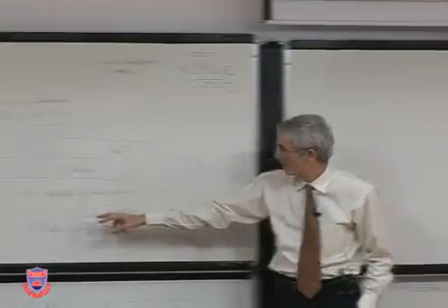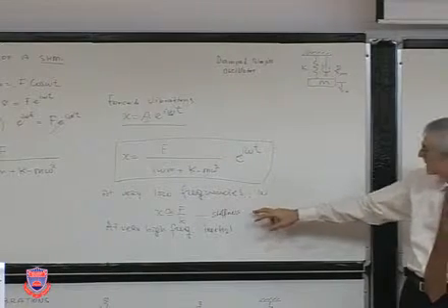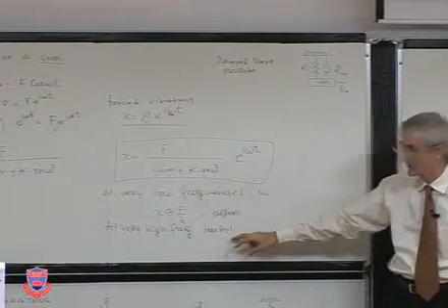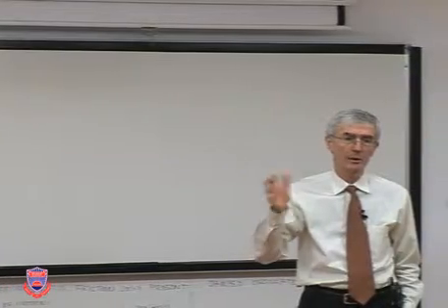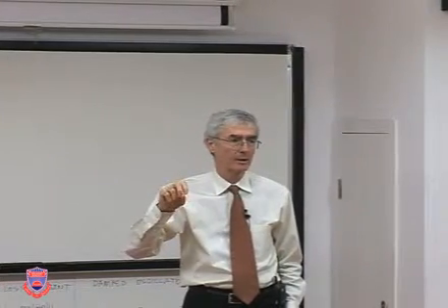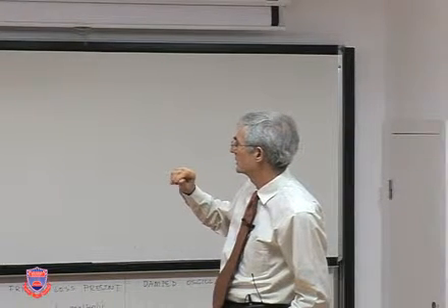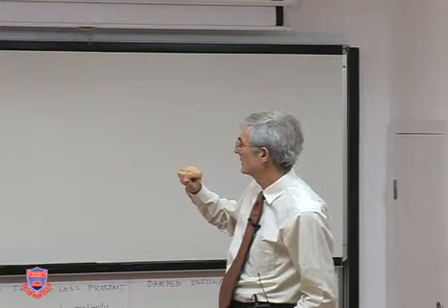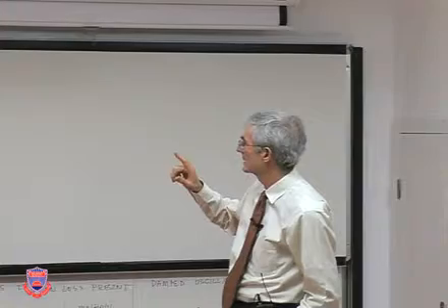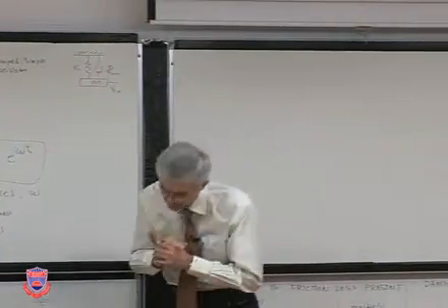So, when we say at low frequencies, it's a stiffness effect, whereas at high frequencies, it's a mass effect. This has relevance to oscillations, how one should influence the sound transmission problems.